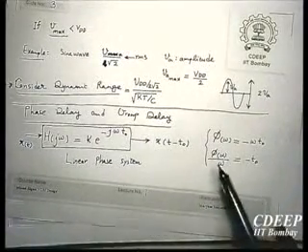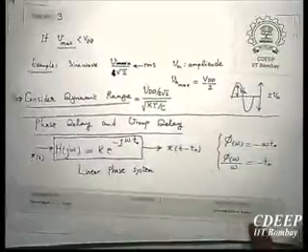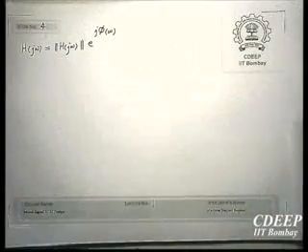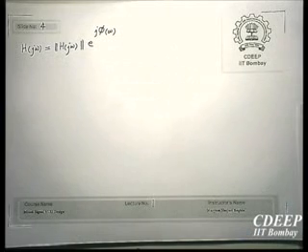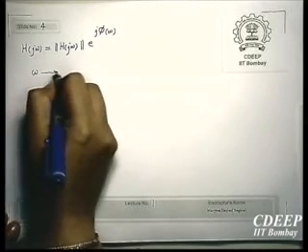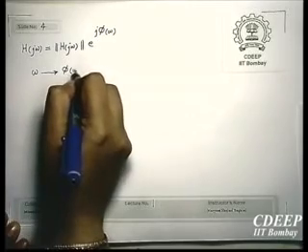Actually, group delay is usually used when I use d phi omega by d omega, and phase delay is usually used when I use phi omega by omega. So therefore we use this. Therefore we want to see that if I have a frequency, for example omega, I get a phase phi omega.